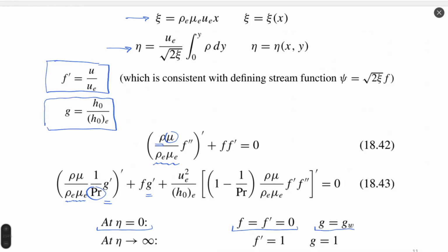And on the wall, we set the enthalpy on the wall, or temperature on the wall. It's equivalent as we set, for example, the temperature on the wall. Enthalpy and temperature are related. Probably you remember, right, that enthalpy is Cp multiplied by temperature. So it's quite an obvious linear relation. Cp is considered constant in this calculation.